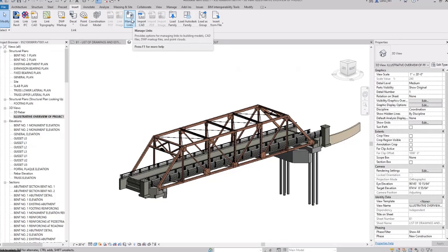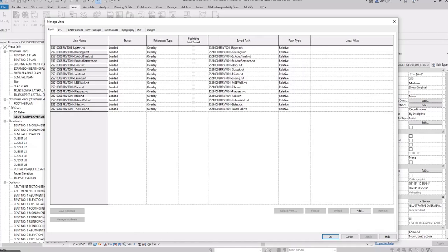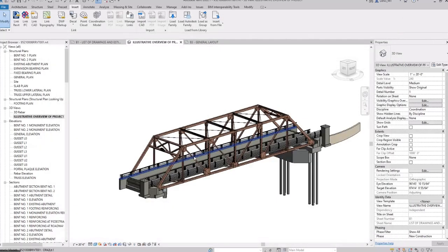But to touch back, I want that direct link to be clear with Inventor on this workflow. 3.14, you'll see all those same links. And so if I had clicked OK, I didn't want to take the time to, but I could have simply updated the gussets here, and then that's real time. A lot of times we're making those small changes, as I showed you on the Denton Bridge, and so that update tool is very powerful. Your dimensions will stick to those parts. Rebar will actually grow and shrink as you change the size of a cap. So it's extremely powerful to be able to do that.